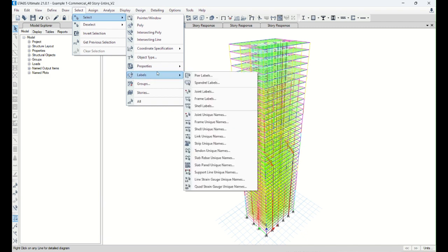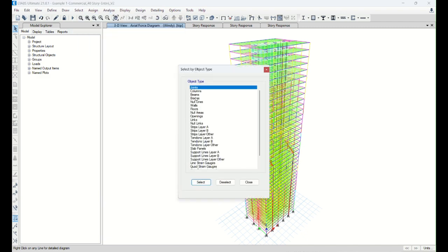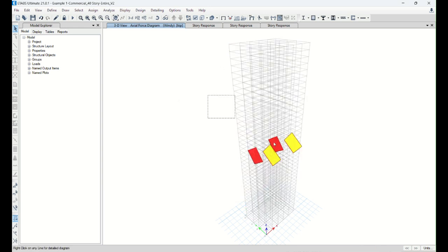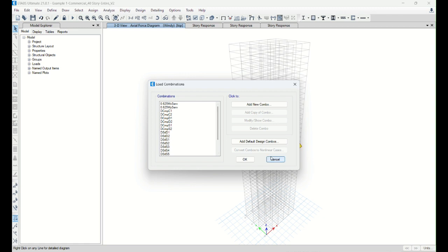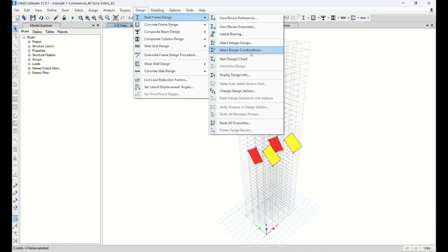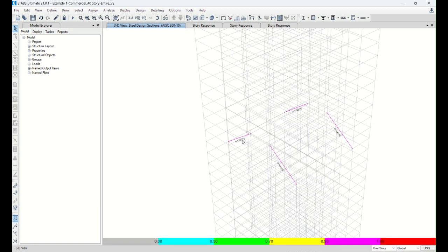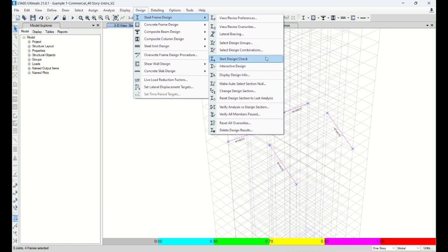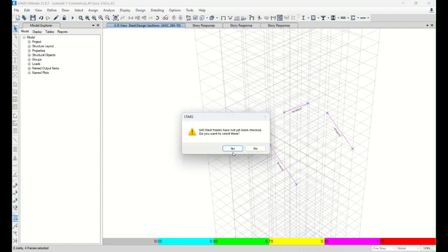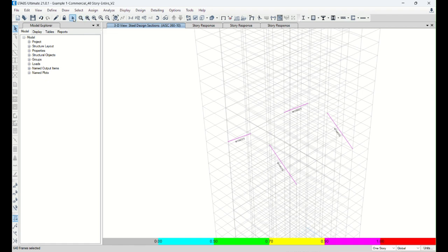You can select the object type bracing, right? And I'm only going to show these elements. Since we have all the load combinations, you can just go to design steel and run it and size. Somehow initially the size is W14 by 370. So we may, same thing, do iterations. I need to check a few things, but I'll just go verify the pass, select, and then rerun it.